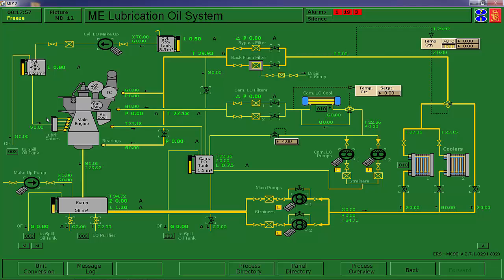Sulfuric acid etches metal from the liner and causes wear. So because we can neutralize this sulfuric acid on big slow-speed crosshead engines, there are other reasons, but this is considered one of the major reasons why they have the lowest liner wear rates in the industry. And liner wear and piston ring wear, those are the big maintenance costs when running one of these diesel engines.